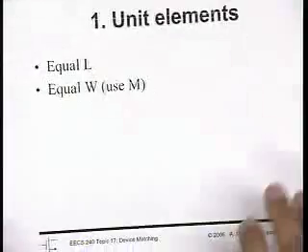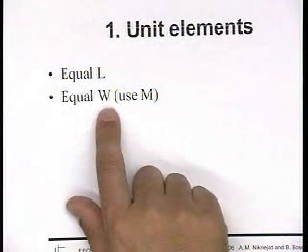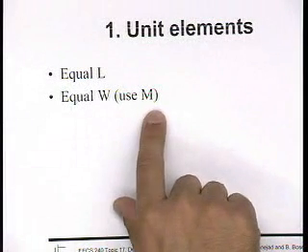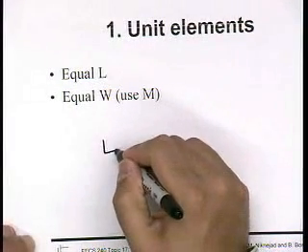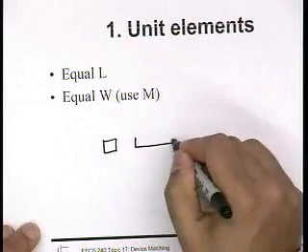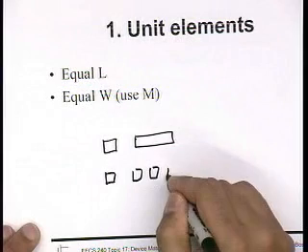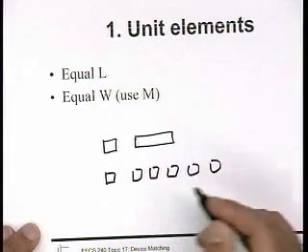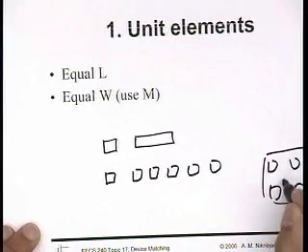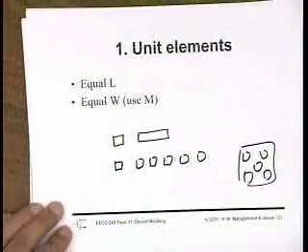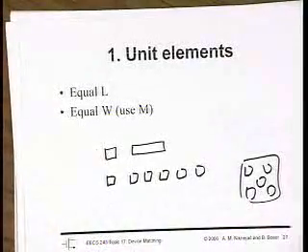So unit element, there's not much to say here, right? Just use the same equal W, and instead of changing W, change M, right? So if I'm doing a matching of, let's say, 5 to 1, this might be the bad way to do it. The good way to do it is like this, and maybe a better way is you tile it like this, and in fact just use even numbers. Avoid using odd numbers. Even numbers let you do things like common centroid.